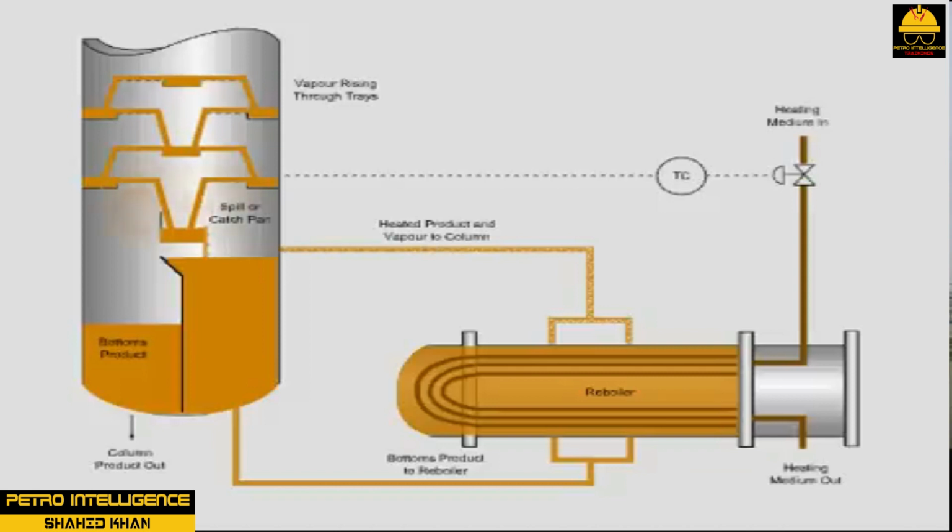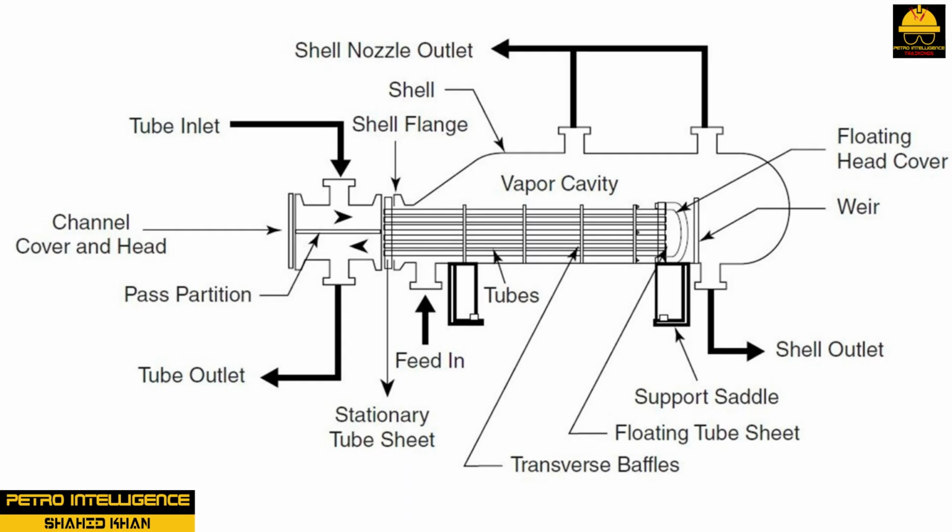As flow enters the reboiler, it comes into contact with the tube bundle. The tubes have steam or hot fluids flowing through them. As the bottom product comes into contact with the tubes, a portion of the liquid is flashed off or vaporized and captured in the dome-shaped vapor cavity at the top of the reboiler shell. This vapor is sent back to the tower for further separation. A weir contains the unflashed portion of the liquid in a reboiler. Excess flow goes over the weir and is recirculated through the system. Kettle reboilers are easy to control because circulation and two-phase flow rates are not considerations.